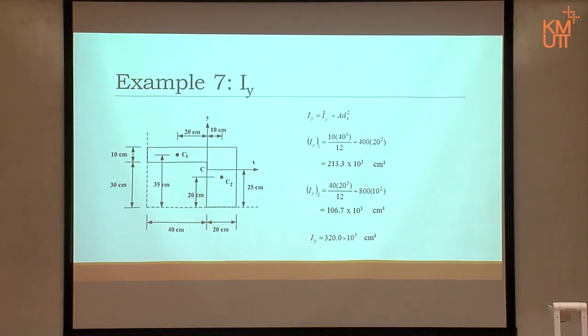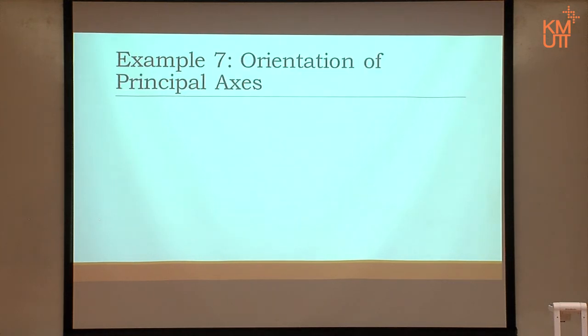Okay. Then now we are ready to move on to the next stage. That is the equation. We already know Ix. We now know Ixy and Iy. Substitute, you see, just substitute it, right? The values we already have, substitute them. Work out the angle.